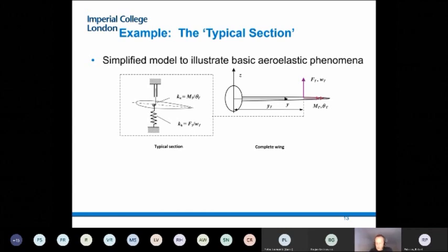So consider this thing on the right is my wind turbine blade sticking out of some nacelle, and then I go around my 100 meters long span. I look at a certain section, Y, and there typically what I will have is this being affected by mostly bending forces, which are trying to pull it out, and torsional forces, which are trying to twist it. You could try to address this problem on the full blade, and indeed that's what we do routinely for analysis.